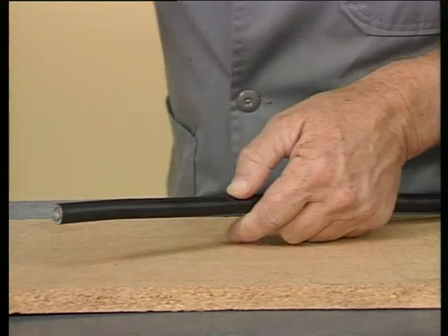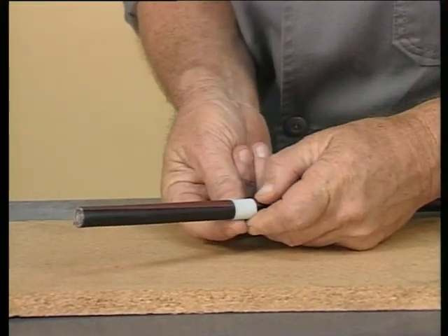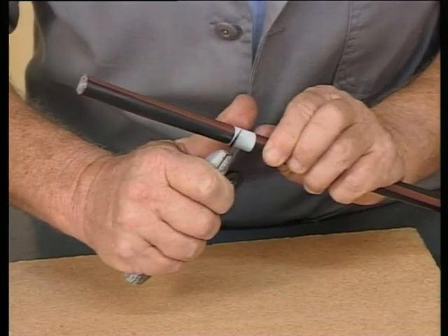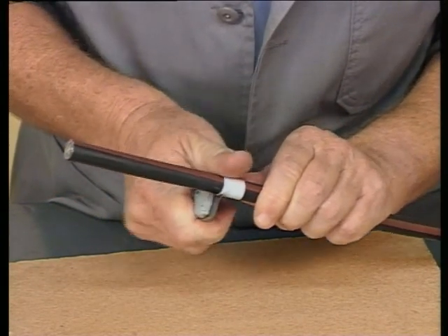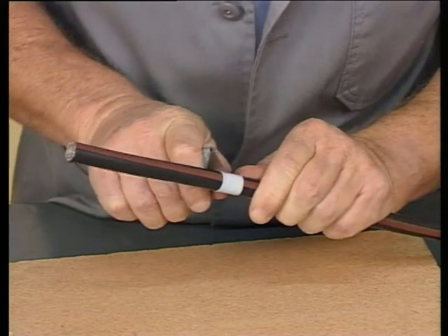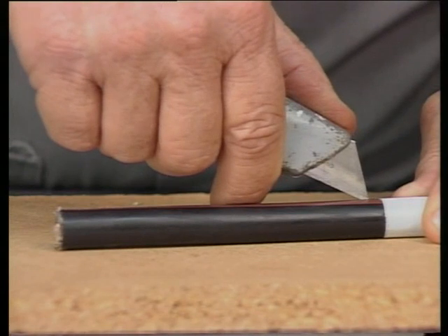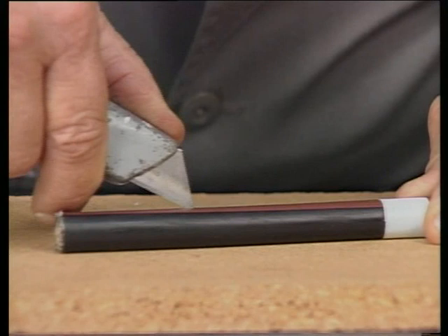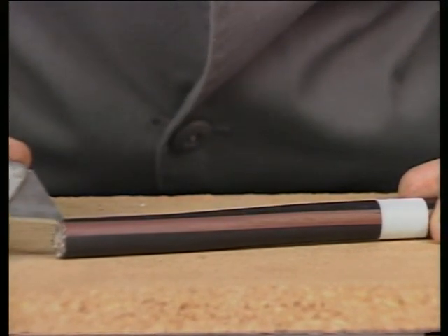Because we want to work neatly, the entry position is first marked off and a wrap of tape used to provide a cutting guide. With the aid of a sharp knife, a ring cut is made through the sheath against the edge of our marker tape. Care is taken to prevent the blade scraping the wire armoring, as this would dull it. A longitudinal cut is then carefully made, and the sheath peeled away to expose its armoring.